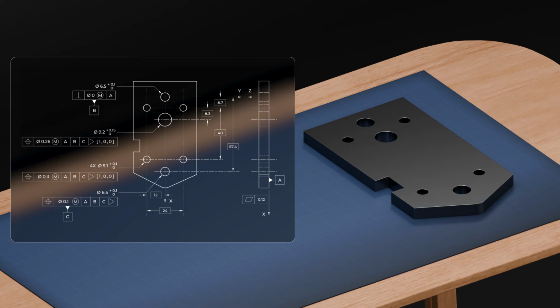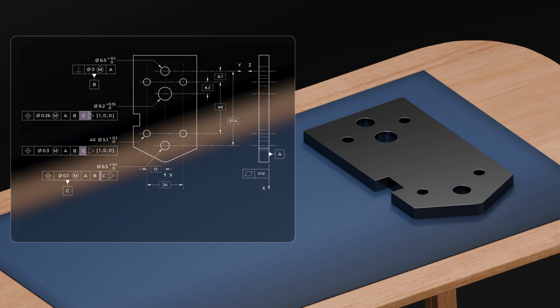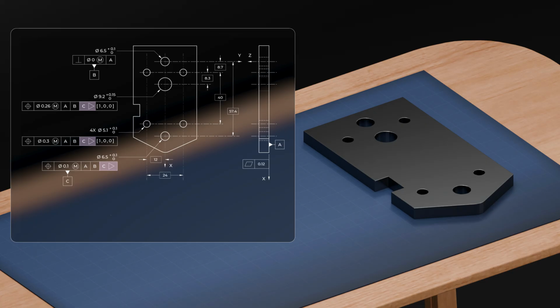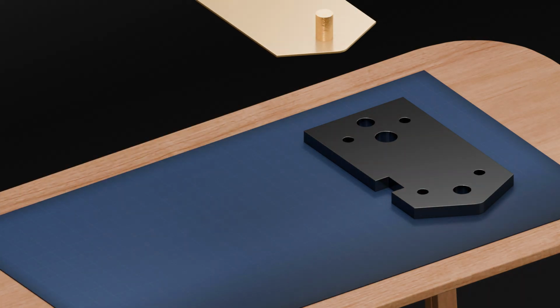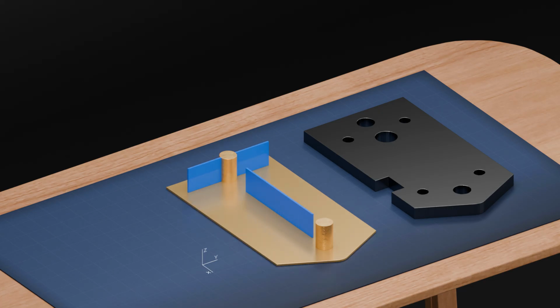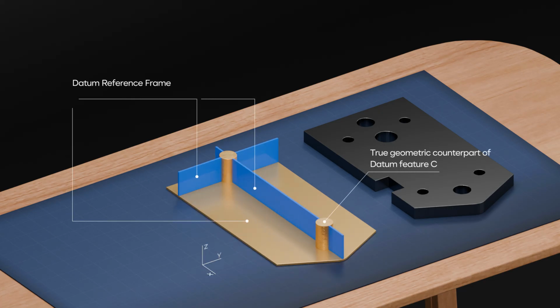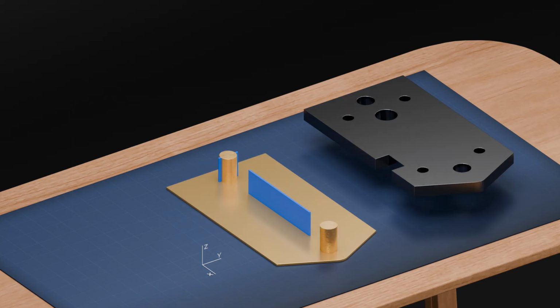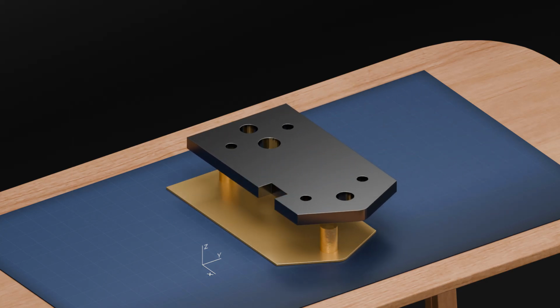These holes are controlled with a positional tolerance, and in the feature control frame, the datum C is followed by something you might see as a triangular arrow head, that little symbol after C. That's the translation modifier. Here's what it's telling us. When we inspect this part, the simulator for datum C, that is, the pin representing C, is allowed to translate, move slightly to get proper alignment with the 5 holes being inspected.